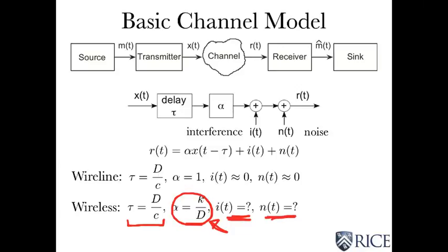Now, we're going to basically assume that we can control the interference by filtering. As we're going to see, in well-designed communication systems, the interference from other communication signals is going to be out of band. What that means is in a different bandwidth, a different range of frequencies than X will be. So we can, just by filtering, get rid of it.